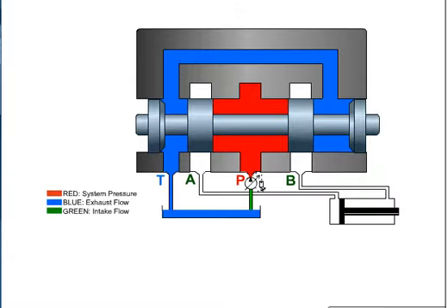Directional control valves are used to start, stop, and change the direction of flow in a hydraulic circuit. Although they may be designed as rotary or poppet style, the spool-type directional control is the most common. This design consists of a body with internal passages that are connected or sealed by a sliding spool along the land of the valve.